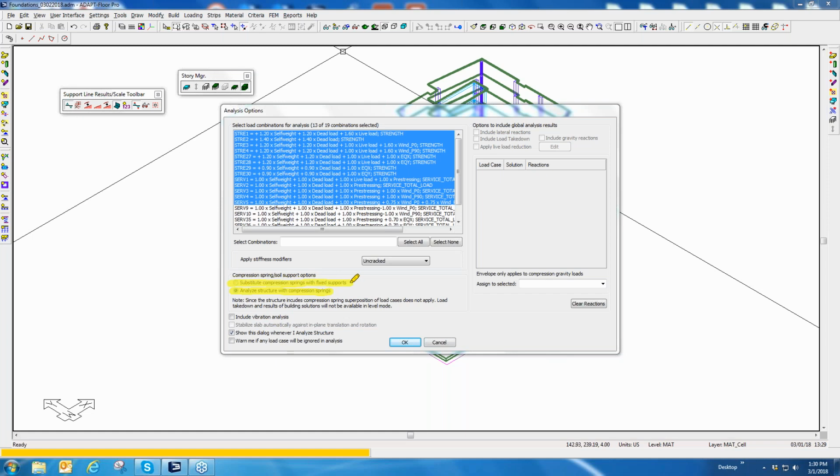If you substitute the springs at the base with fixed supports, you have basically zero displacement at the bottom of the slab. And then in the indirect solution, you must go back to single level and again reapply the reactions like we just did for tributary. So those are two different approaches. We're going to do both. You might ask, well, what's the difference? Why would I ever choose the indirect solution for a model?